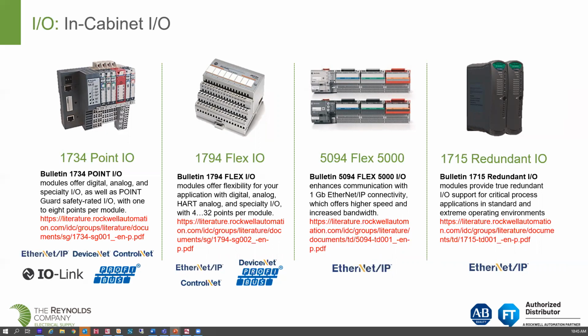And the 63 nodes is kind of important, because any of you old school guys who remember DeviceNet, that was the limit on DeviceNet, because that's basically what we're running across the backplane for the comms on it. So this is really nice IO, especially when you have a small footprint. If you just need to put IO in a junction box, this works perfect for you.